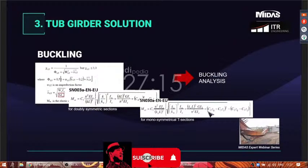However, there are two ways in which this phenomenon can be dangerous for composite bridges. The first occurs in continuous bridges, where the negative moment can compress the lower flange that is not constrained by the slab. And the second one can occur during execution, when the steel section is alone and we are casting the concrete of the slab.